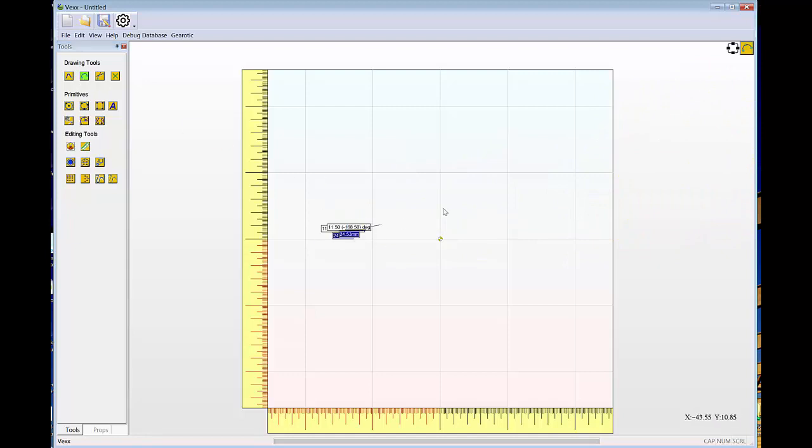This goes as well for arcs, but the tip boxes will change. As you can see, as I'm moving my mouse, it's as if I'm drawing a line at the moment, but when I set that first line, which I could have set by typing into the tip boxes, I'm now asked for things such as radius. And I can enter a radius, 50 millimeters for example, and our arc will complete with a 50 millimeter radius. So you can always use the tip boxes to quickly type in more accurate dimensions of things that you wish to create. In Bezier curves, the rules are the same. You can type in coordinates for a distance and angle to the point that you wish to set, and a Bezier curve will be created from the entries that you make.